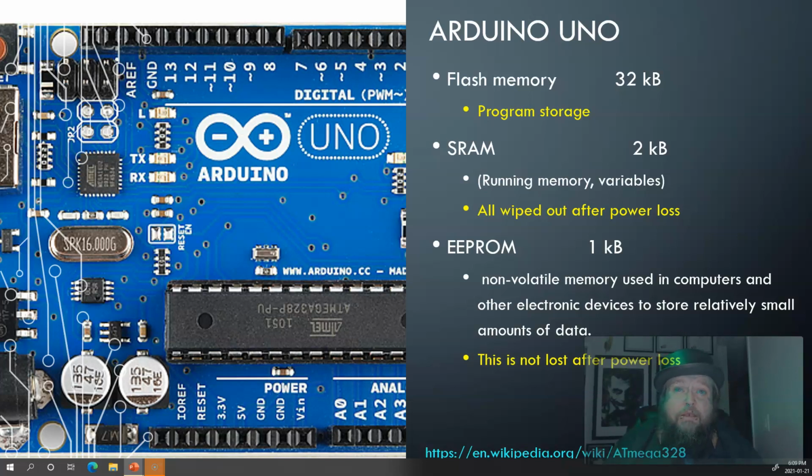When it's running, for your variables and your data structures that you're storing on it, you only have 2 kilobytes of storage. And this is what I mean, that you can't just make an array that's massively large. You have to remember that on physical hardware, data, like an integer like 1, or saying something is an integer, takes up a specific amount of memory, a specific size. So we need to worry about that as well.